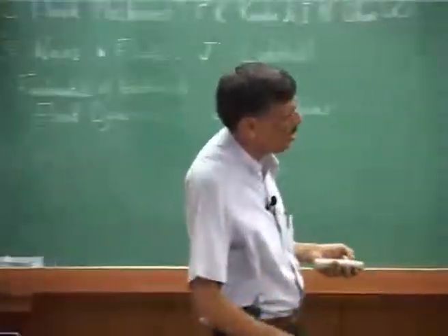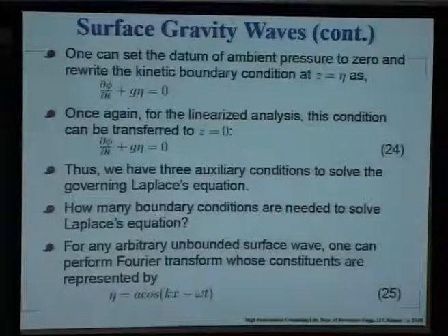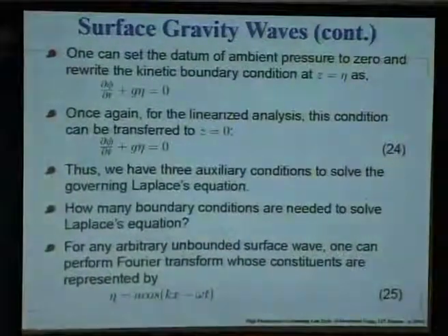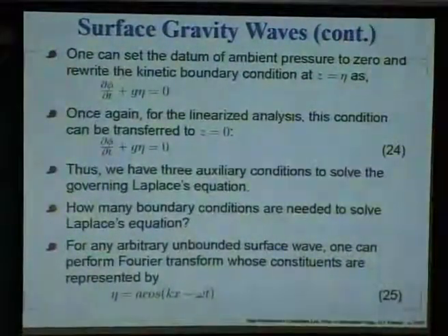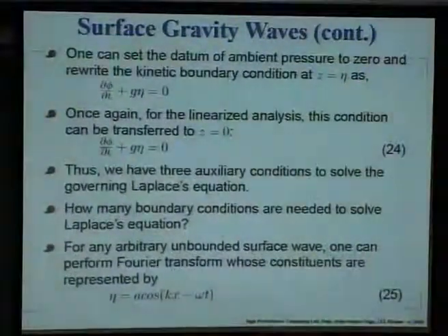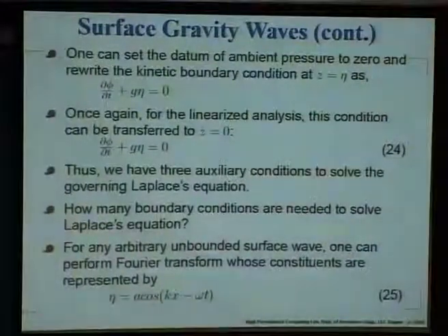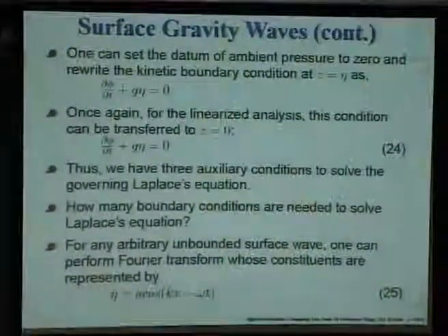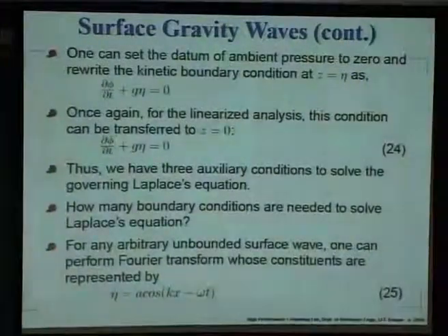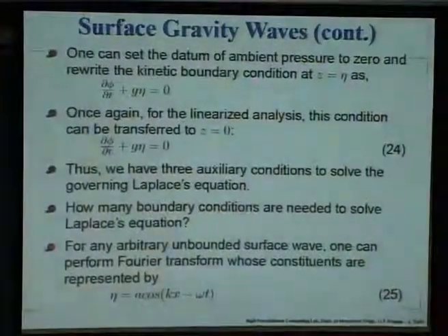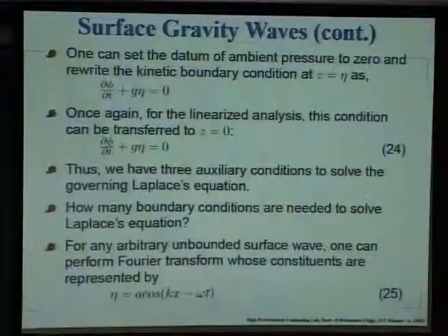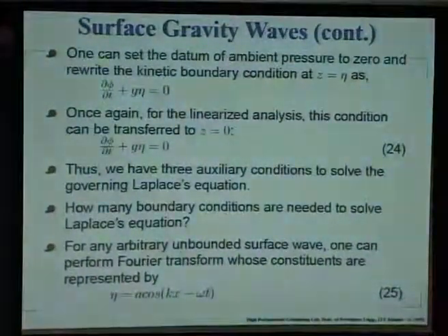Okay. So, we also look at the pressure variation in terms of some datum. The datum is given by rho gz. What we could do is, above in the air part of the problem, put that pressure equal to 0. Okay. So, that is your datum. Then the excursion of pressure would come through this term. One part is due to the variation of the velocity field because of this unsteady deformation here, and the unsteady deformation also brings about the change in potential energy. So, that comes through that term.